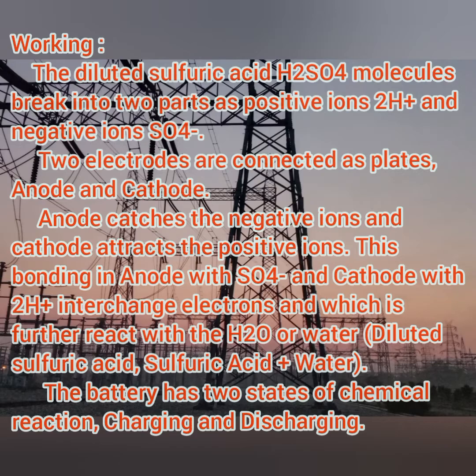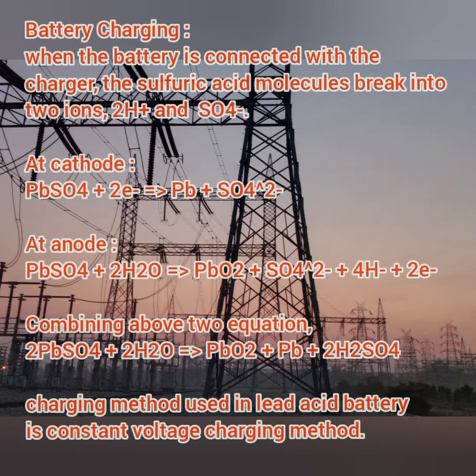Coming up to the charging process. So battery charging: when the battery is connected with the charger, the sulfuric acid molecule breaks into 2H plus and SO4 minus, as I said earlier. So charging, in the sense converting the electrical energy into chemical energy and storing it as chemical energy.